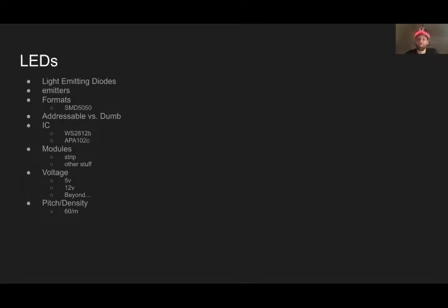But if you can pull off a well-made, robust wearable using LEDs at 144 LEDs per meter, I will be seriously impressed, and it will look spectacular. It's just a challenge. So the other option is typically 30 LEDs per meter. That would be half the resolution that you're seeing here, much less dense, also cheaper, slightly easier to repair. So there are trade-offs here.